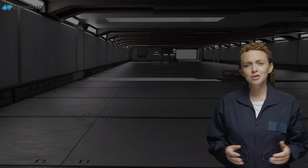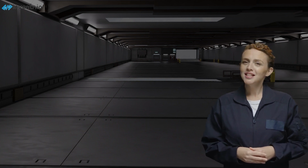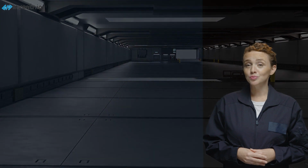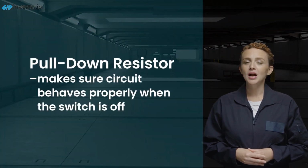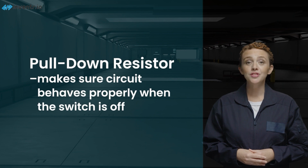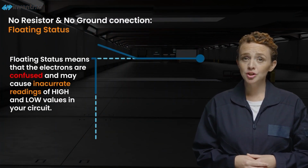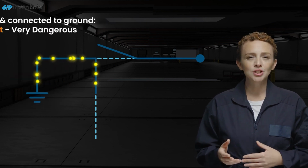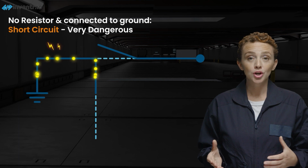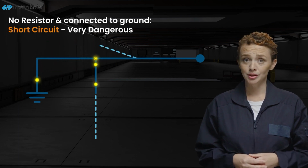Moving on. The extra resistor. A keen observer, aren't you, Explorer? You see, the extra resistor we're talking about is what we call a pull-down resistor. Its job is to make sure our circuit behaves properly when the switch is off. Without it, our switch being in the off position could cause our circuit to get all wonky. Imagine it like a crowd of electricity not knowing where to go and causing a ruckus. We certainly don't need more chaos around here.